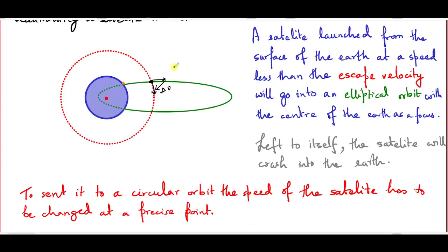Let me point out that here we have made an assumption that the rocket actually produces an impulse. It burns very, very hard but for a very short interval, so that the satellite doesn't change its position while it changes its velocity. Such impulsive thrust makes calculations a lot easier. However, in a real life scenario, you might even have to consider situations where the rocket is burning for a much longer time, maybe in several stages, and the corresponding calculation of the final trajectory will be quite complicated.